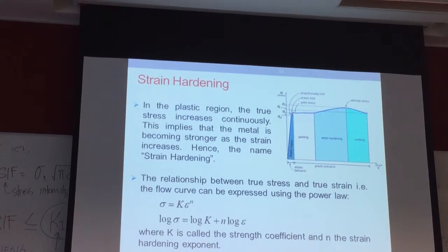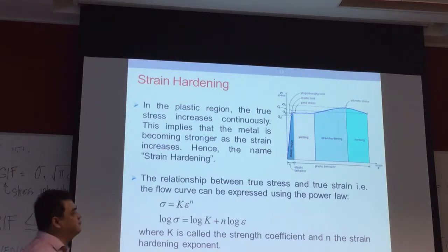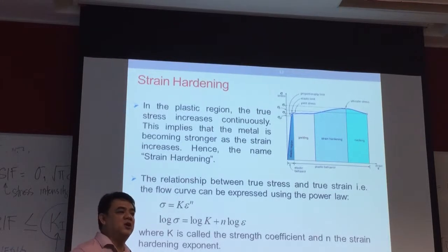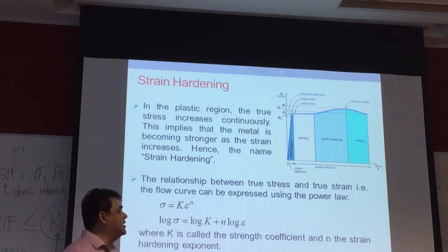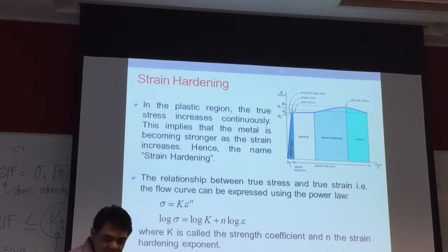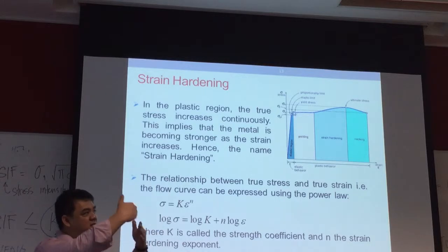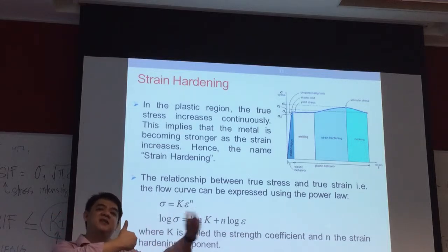So, when does plasticity start? Plasticity starts after your material has yielded. That's when you have plasticity. Well, previously we mentioned it's just important for manufacturing engineers. But in some cases, it's also important because if you want to stretch the application of your material a bit, you may want to know until when, after that elastic region has been reached. So that yield criteria is your boundary between elasticity and plasticity.